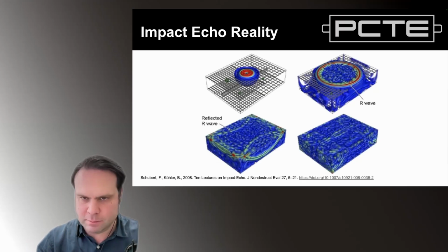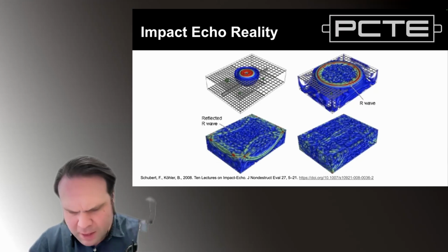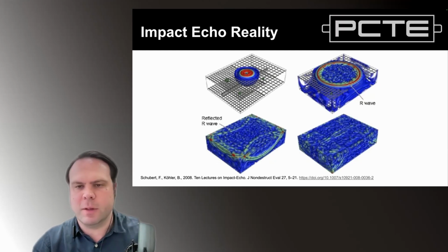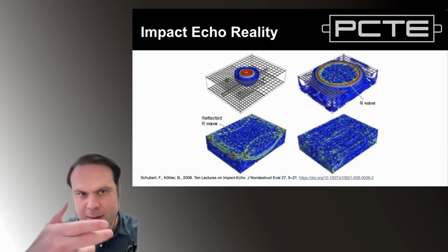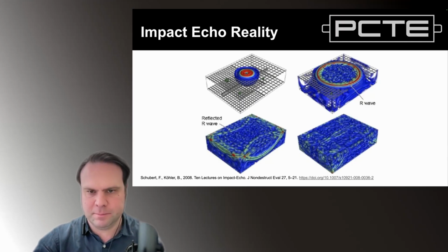And if I get a thicker geometry like a beam or a column, I like to be further away again, maybe a good 300, 400 millimeters, just to limit the influence of these reflections from the edges affecting my test.